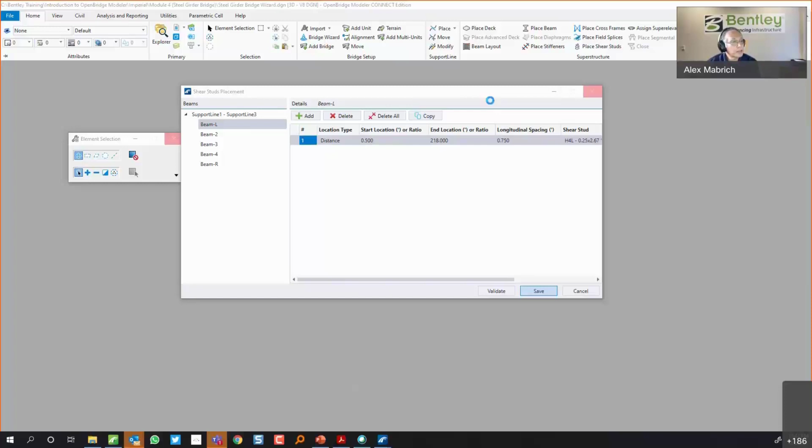Oh, yeah. That's a quick question, a good question, Amir, here. What about a non-standard beam? Well, actually, that's what we use. We use a non-standard beam. That's a built-up shape that we use, right? So you can define the top flange, the bottom flange, and the web. But also, you can define a beam with haunches, right? So you can also do that and configure the beam as it's varying. So you can still do that.